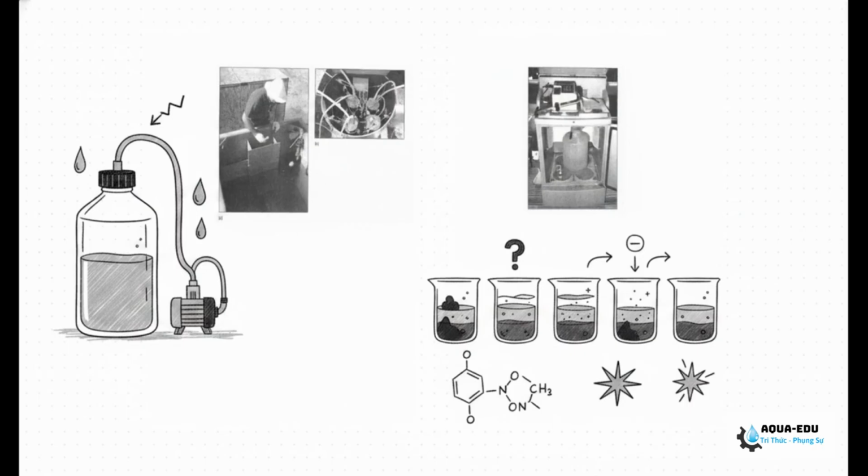You've got to get out there with your auto samplers and pull the hard data. Run some rapid jar tests so you can visually confirm exactly where the chemical separation is failing.